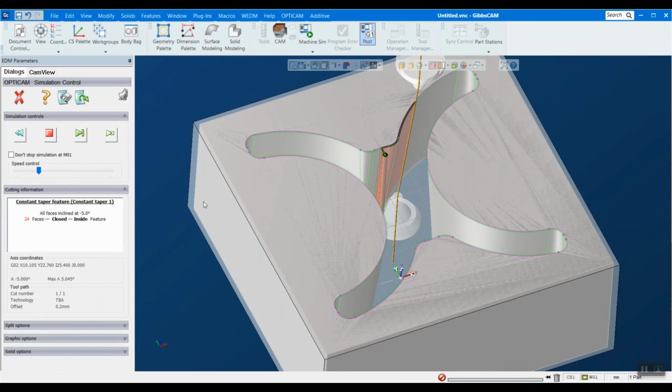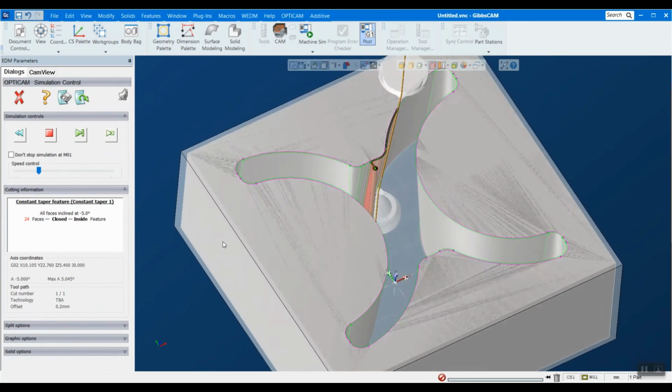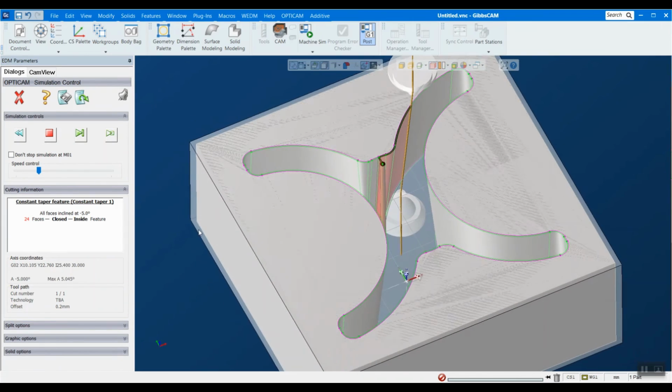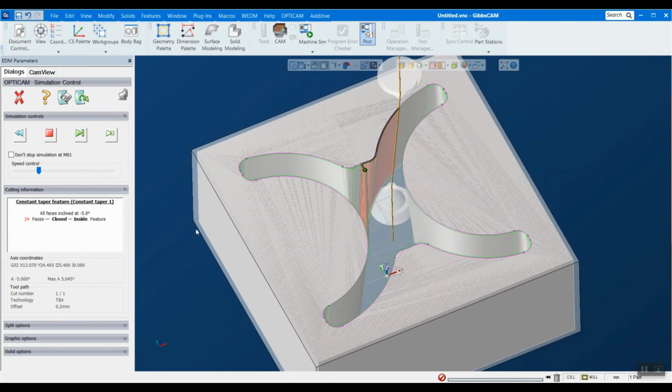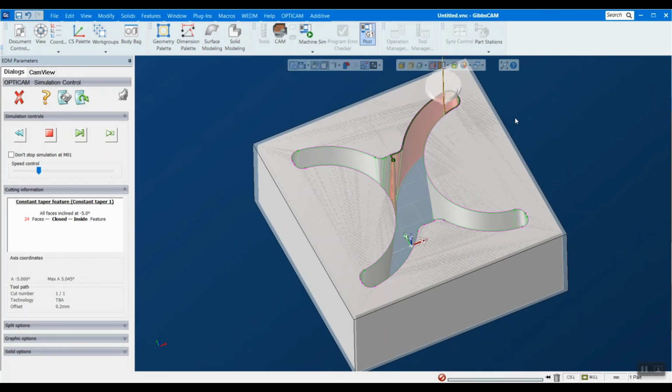And you can see it's automatically angling, automatically following that line. It actually automatically detects if this is a 4-axis part or a 5-axis part. If it's a 5-axis, it'll error out, say, hey, you can't do this with the wire part. It'll let you know that this surface isn't straight. All right, and then it does the same kind of thing.